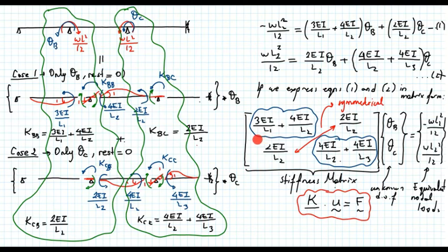And remember, this coefficient comes from member AB. It's the contribution of member AB. It shows the resistance of member AB. The second coefficient comes from member BC. It is the resistance of member BC. And all these contributions coming from each member should be positive also. So you should never see a plus coefficient and a negative coefficient. It will never happen. Okay?